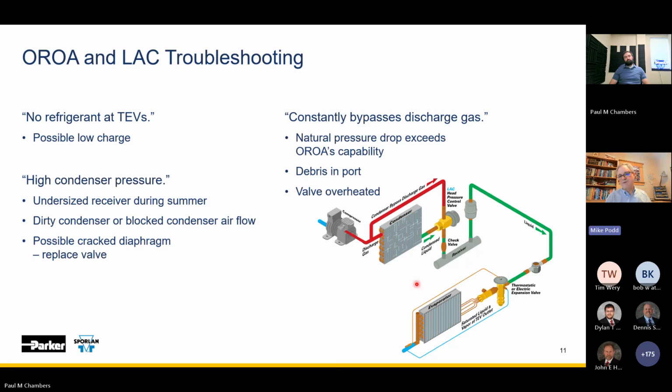Then you've got to calculate how much refrigerant is required to flood that condenser completely full. Then determine on your coldest day how much needs to be flooded. So it might only be 80%. You might only need to flood that condenser 80% on a cold winter day.